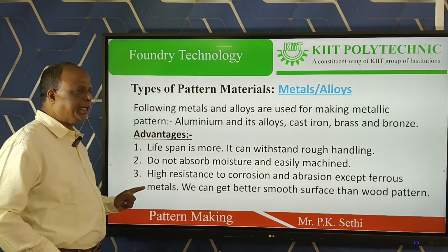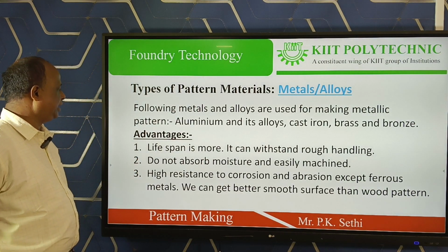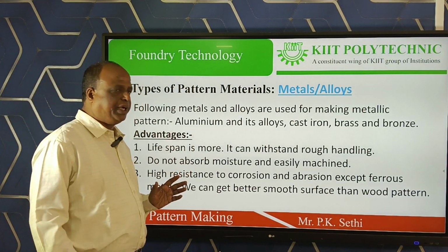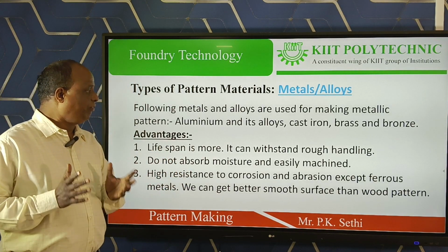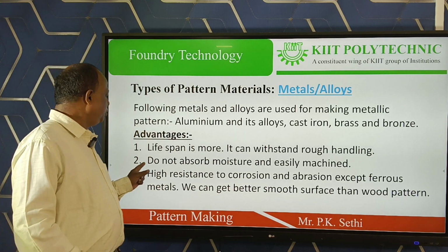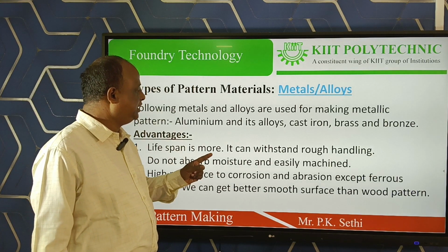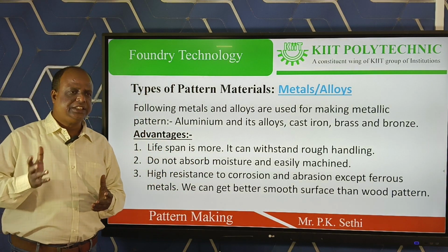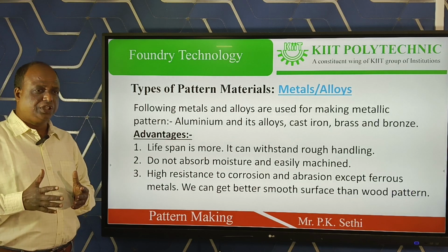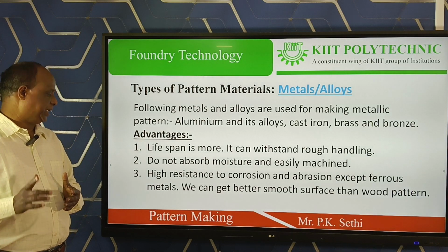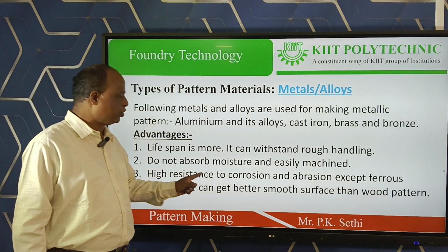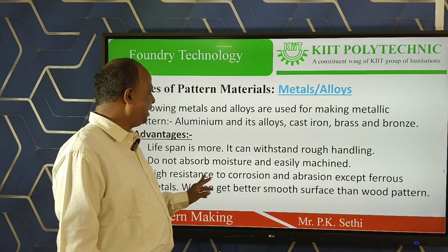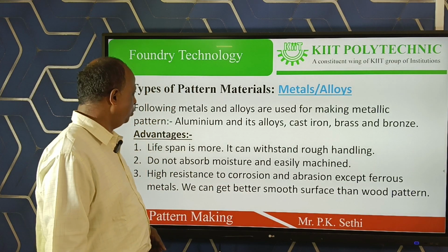Next, what are the advantages of metallic patterns? The lifespan is longer, and they can withstand rough handling. Number two, they do not absorb moisture and are easily machined, during working conditions or during storage, except for the ferrous metals. They are highly resistant to corrosion and abrasion, except ferrous metals, so we can get a better and smoother surface than wood patterns.